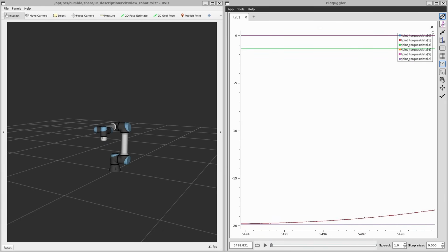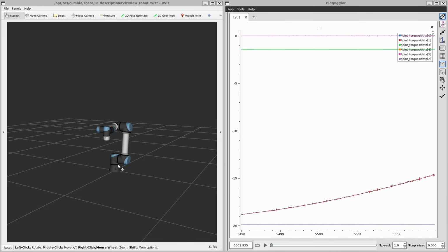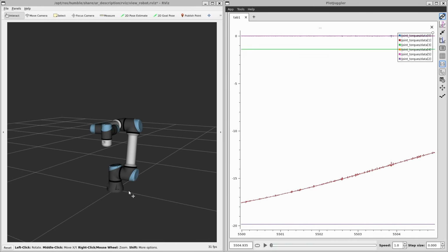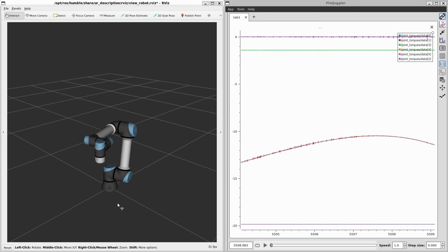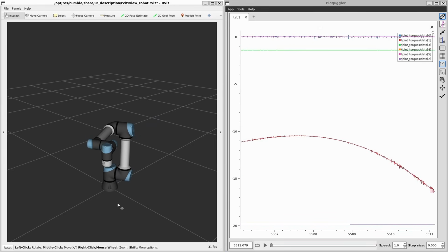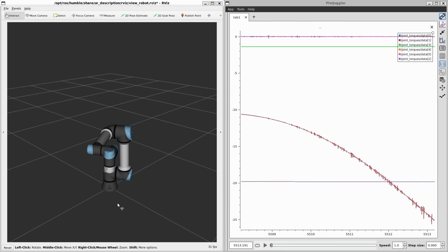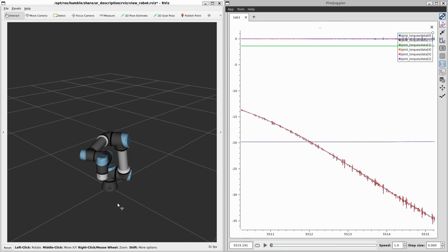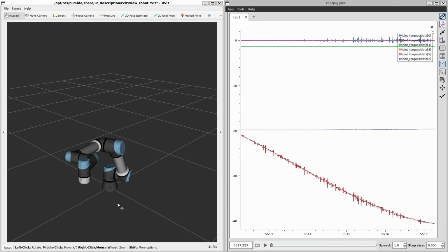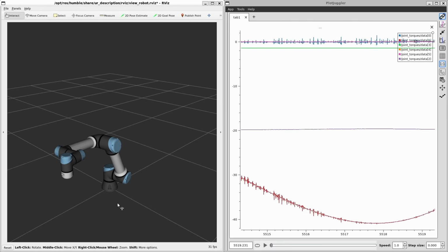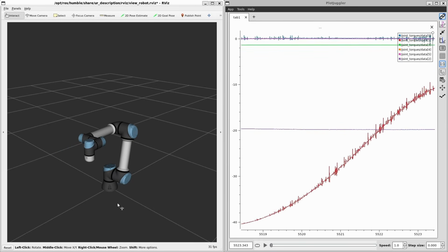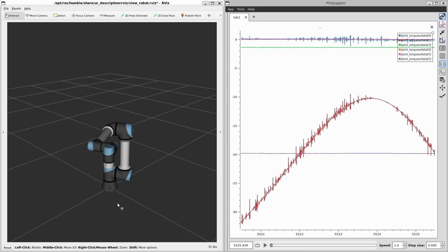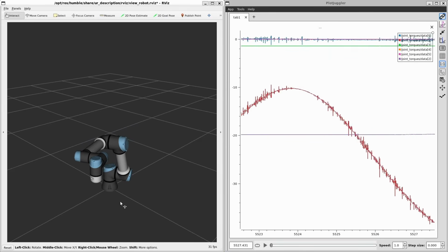During this motion, it's going to plot the torques that it's using to generate that motion. So you can see right here as it's drawing the circle, the torques are being plotted. Most of the torque that's being applied that varies is going to be J2 because you could see that it's moving closer and away from the base. That's why J2 sees most of the torque difference. Some of the other torques, because of how slow it's moving, are just basically trying to maintain the current position, so you don't see too much change in those torques.